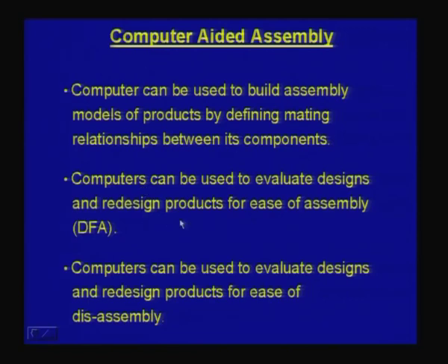If we go one step further, computers can be used for what is called design for assembly, or the DFA concept. As a part of DFA, you are evaluating various designs or various configurations of designs for ease of assembly. So, if I have a number of ways in which a configuration of a product can be designed, then one can select or optimize from the ease of assembly point of view.